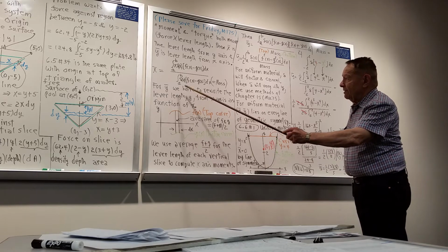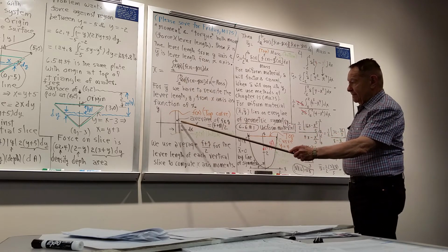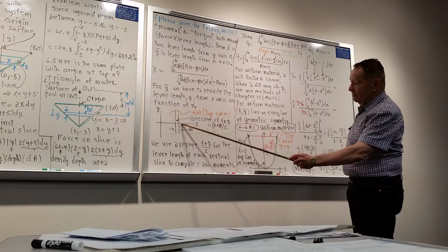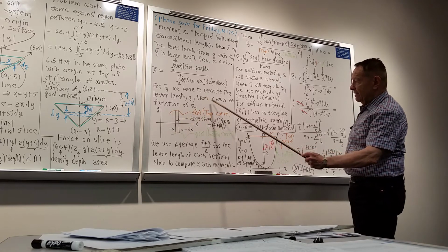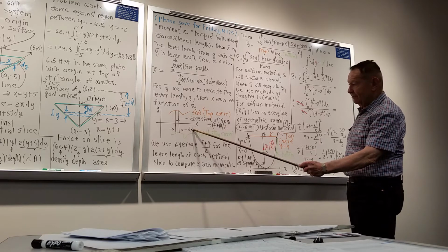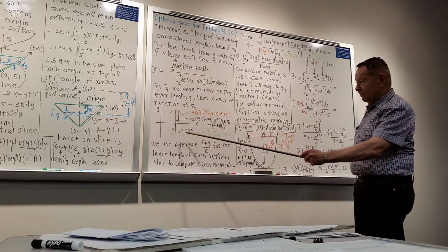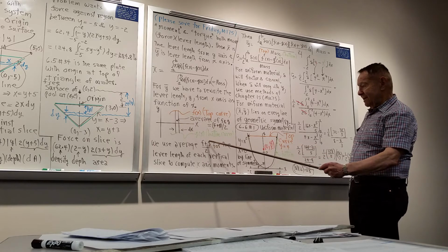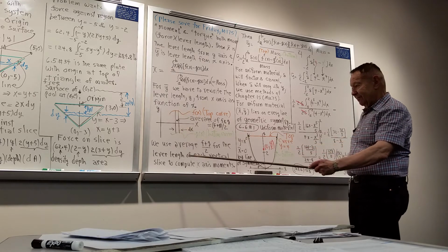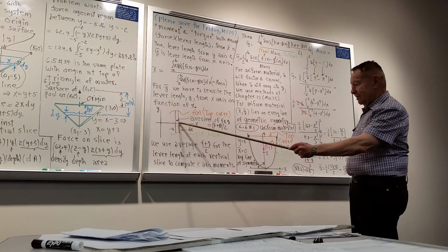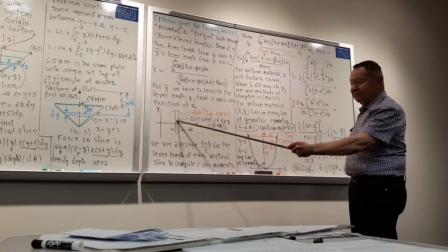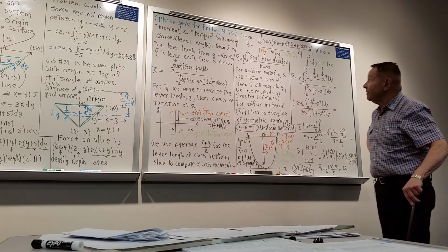And in the y bar, in the same way, what you have to do is write your lever length from the x-axis as a function of x, because these problems are set up to integrate with respect to x. So we use the average height of the representative rectangle as the lever length of each vertical slice, measured from the x-axis to wherever this average point is.